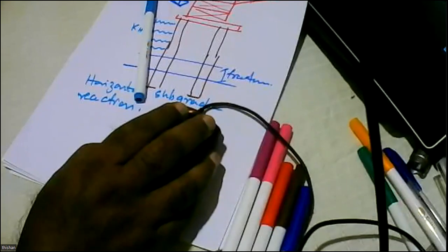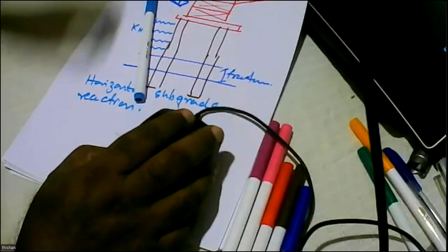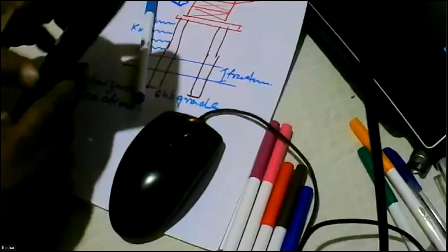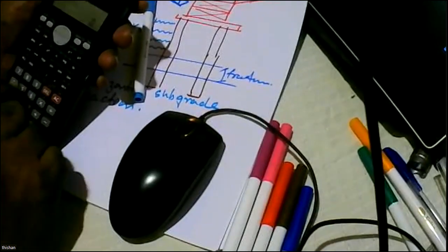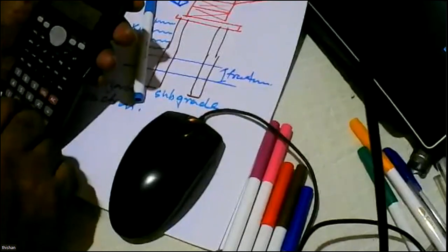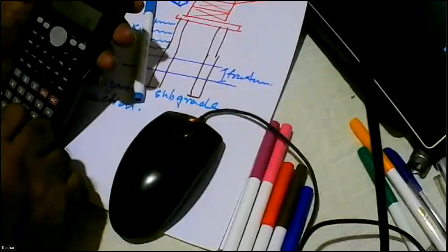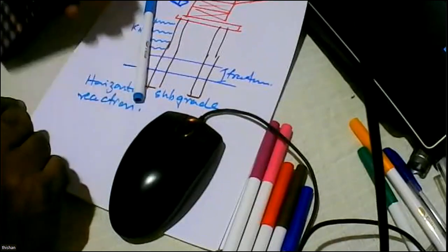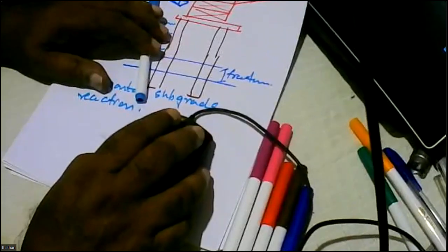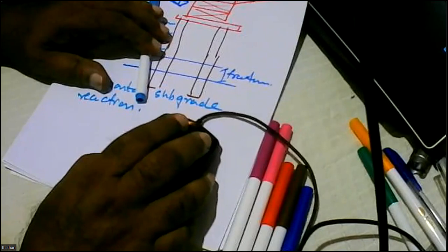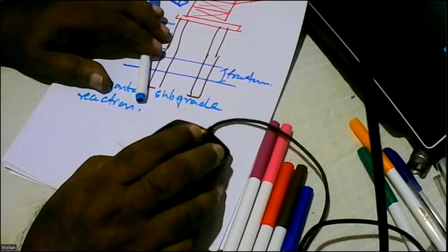Now, let's say we have an SPT of about 15, which means the cohesion of the soil will be 4.5 times 15, which comes to about 67.5. On the other hand, you can also say it's 5 times 15 and use a value of 75. No harm. Because when you look at this, you can see even if you use a value of 5, there are a lot of results falling in that region. But if you use 4.5, it may be even better.